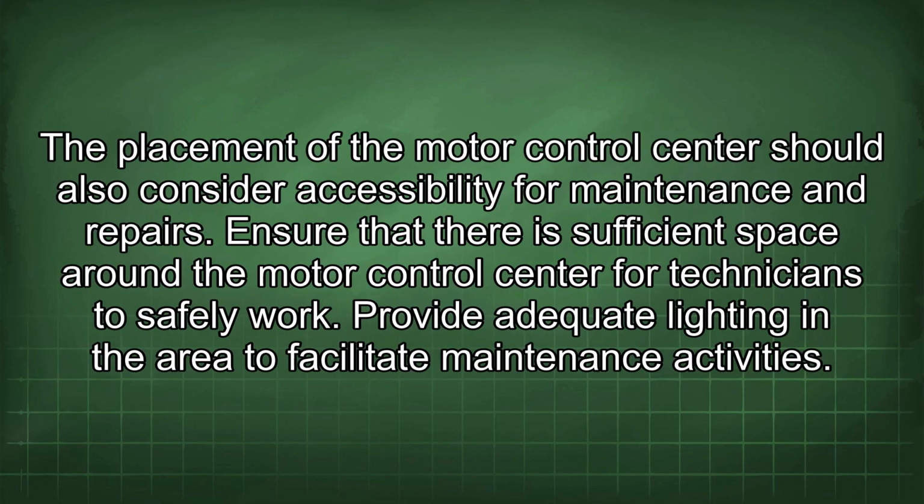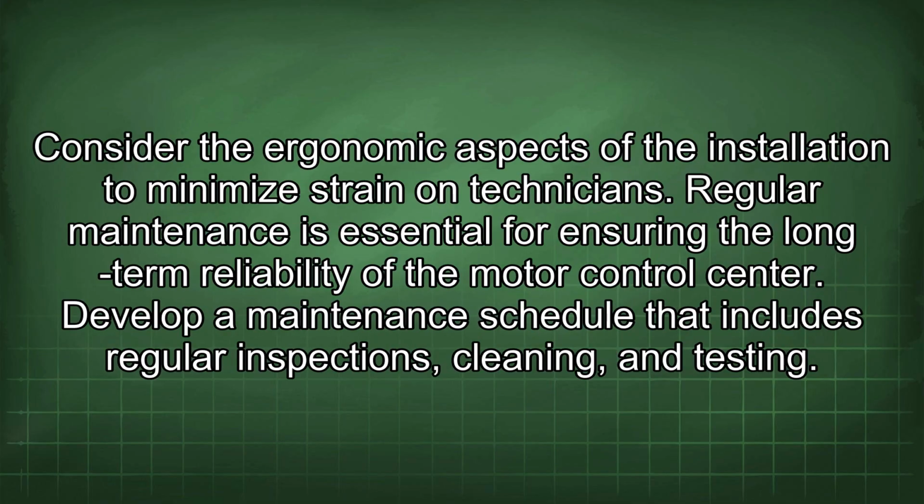The placement of the motor control center should also consider accessibility for maintenance and repairs. Ensure that there is sufficient space around the motor control center for technicians to safely work. Provide adequate lighting in the area to facilitate maintenance activities. Consider the ergonomic aspects of the installation to minimize strain on technicians.